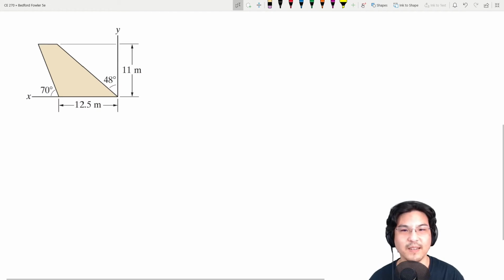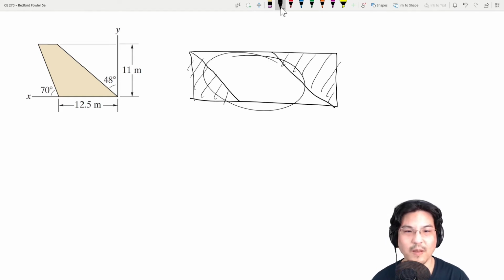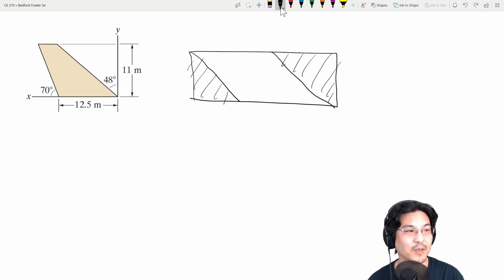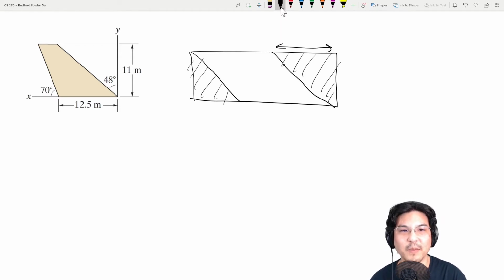It looks like one big rectangle with a cutout here and a cutout here. And cutout meaning negative area. Right, so then we're left with this shape, the vertical stabilizer. So, and then let me get the dimensions back here, right?